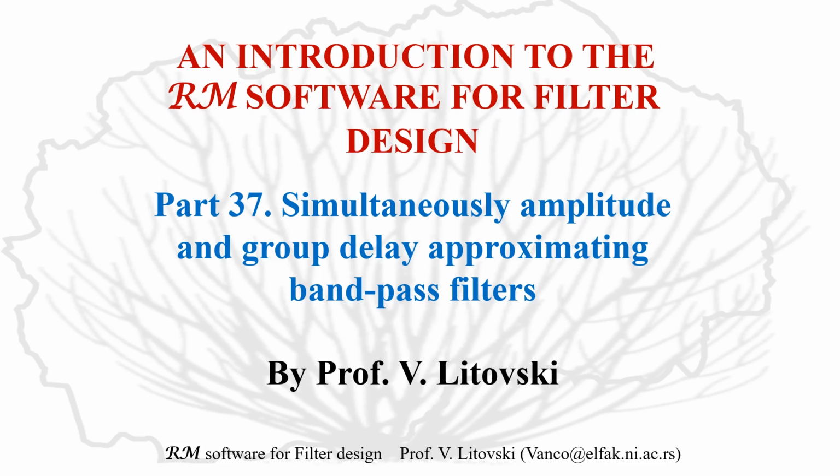The amplitude characteristic on its own will be allowed to have transmission zeros on the frequency axis, which will boost the selectivity.